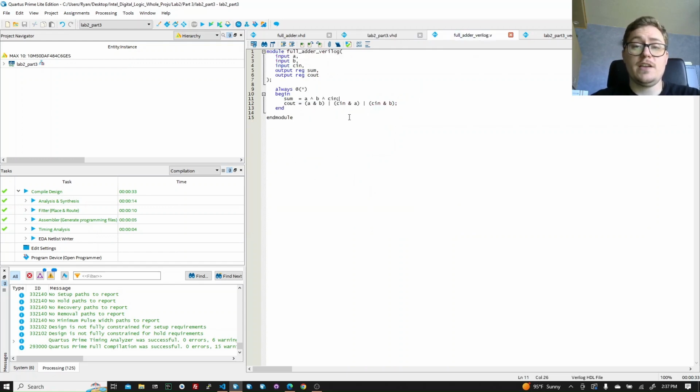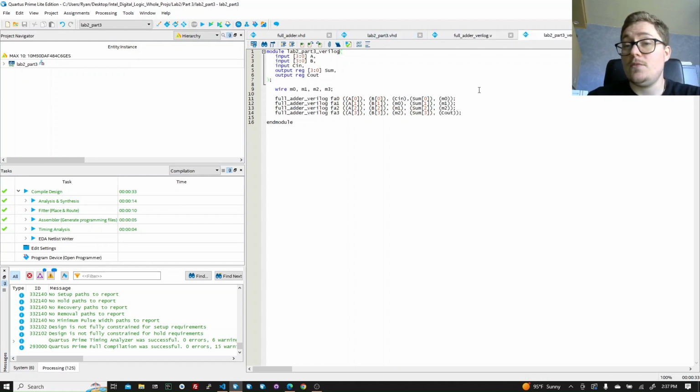All right, and that's basically it, but here is the Verilog version of this. Basically we are XORing the same thing. I used a data flow model as well, and we also have the similar port mapping for the full adders in this Verilog instance. Again, I've always said it, but going from one RTL to another is incredibly easy, I think. It could take a lot longer if the circuit were complex, but this is an incredibly simple circuit, so it was very easy to move between the two. But I have VHDL and Verilog done, so that's kind of nice.